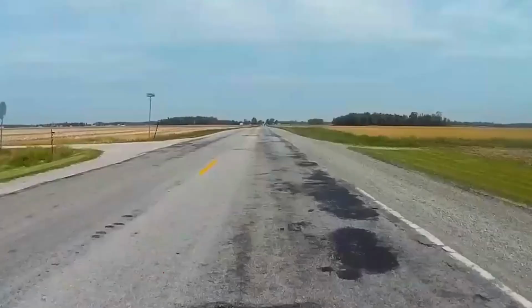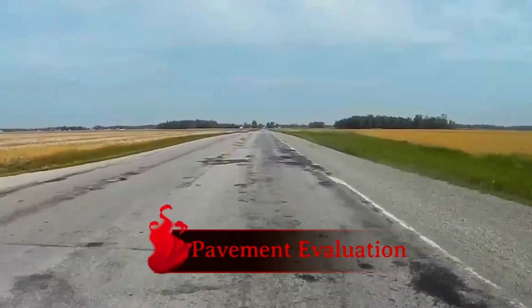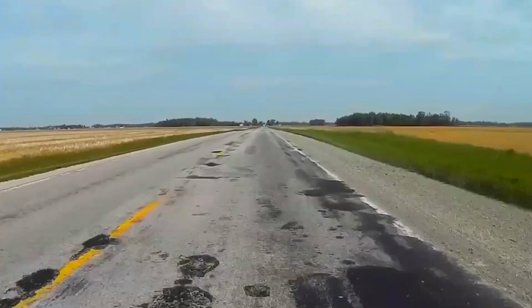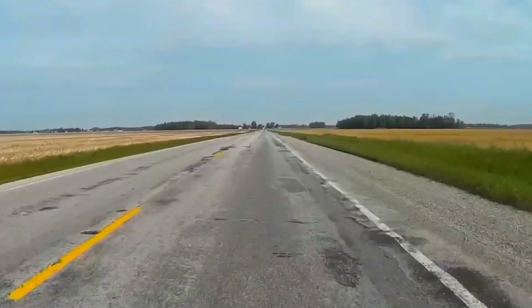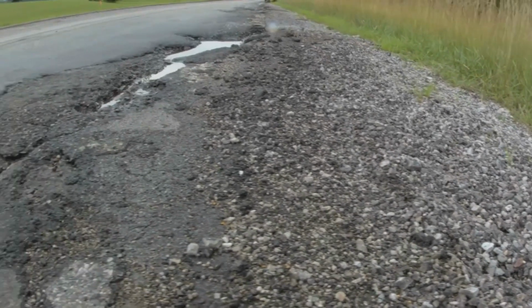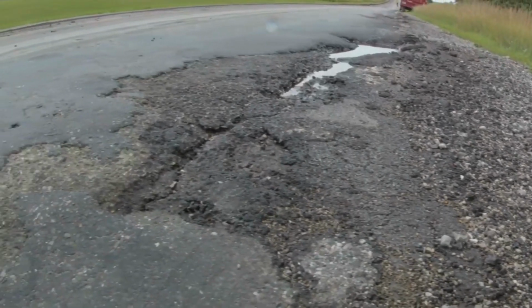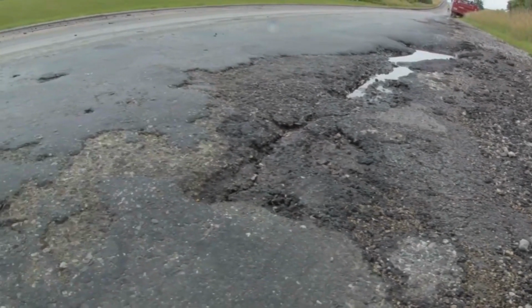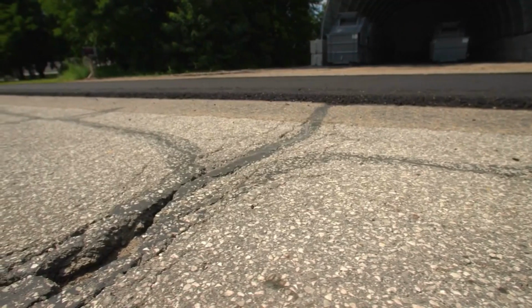Step 1. Pavement evaluation and preparation. Before applying an overlay, engineers assess the existing pavement condition through visual inspections, core sampling, and deflection tests. If the surface has minor cracks and wear, an overlay can be applied directly. If there are deep cracks, potholes, or structural issues, pre-overlay repairs are necessary. Once the evaluation is complete, the road is cleaned and prepared for overlaying.